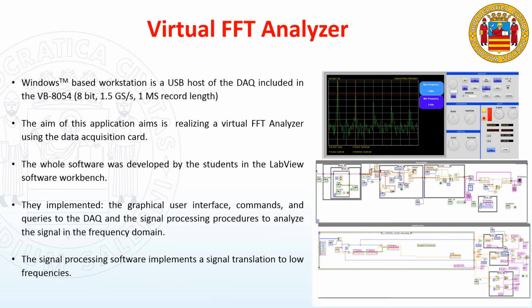The first automatic measurement station was programmed to realize a virtual FFT analyzer using the data acquisition card provided by the virtual bench previously described. The whole software was developed by the students in the LabVIEW environment using the Workbench software. In particular, they implemented the graphical user interface, commands and queries to the DAQ, and the signal processing procedures to analyze the signal in the frequency domain. The signal processing software also implements a signal translation to low frequencies.